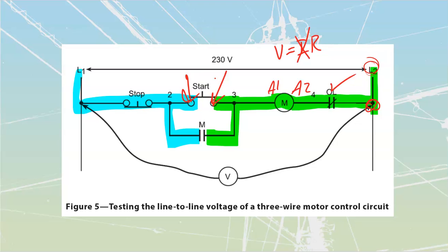So I'm going to check it on that actual button. If I'm not getting that 0, if I'm measuring 10, 20, 30 volts across here, that probably means that I've got bad contact inside of here. So I'm just going to check that, pull that thing open, replace the contact block on the back of the switch, etc. Because sometimes it's just a small amount of dust and dirt inside of there that prevents us from generating enough current to close in our coils over here.